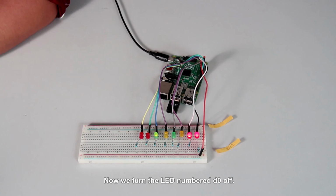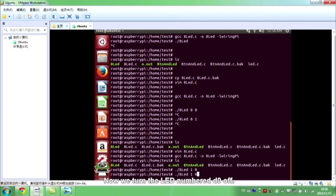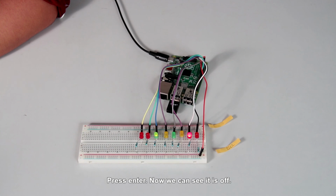Now we turn the LED number D0 off. We can see it is on. The first parameter is the pin number, that's 0. The second is the pin status. We write 1, press enter. Now we can see it's off.